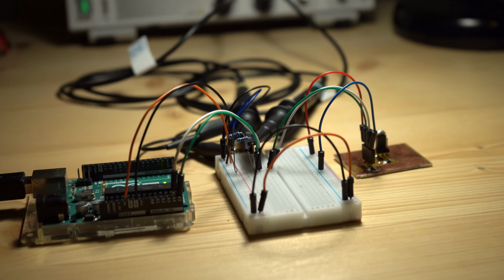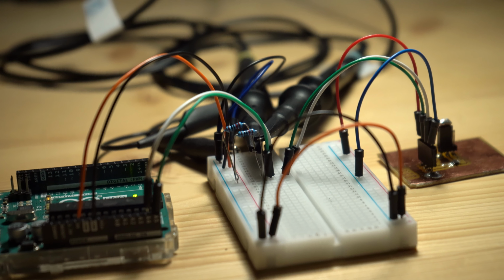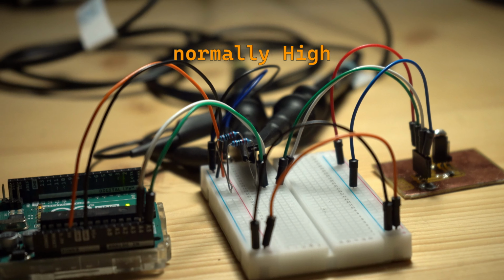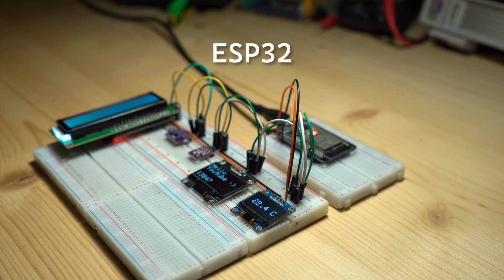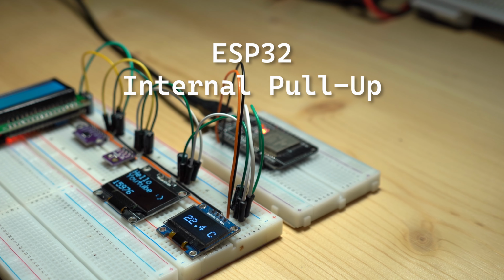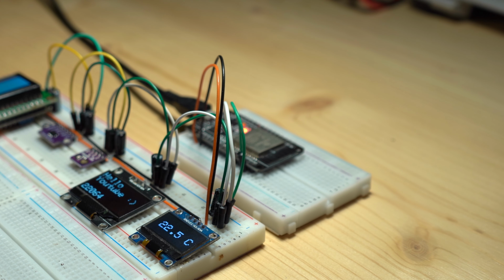When a device pulls the data or clock wire low, the resistors let the bus return to its normally high state. Without pull-up resistors, the I2C bus would float and communication would be unreliable. Note that some microcontrollers like the ESP32 have internal pull-up resistors, thus not needing external ones. However, it's still best practice to add external pull-ups.